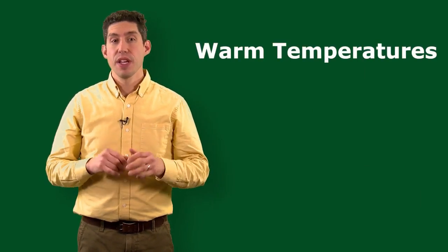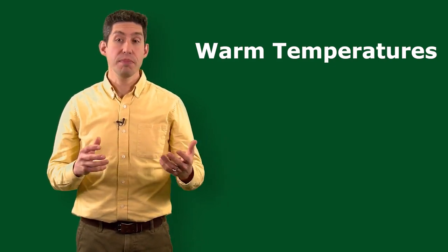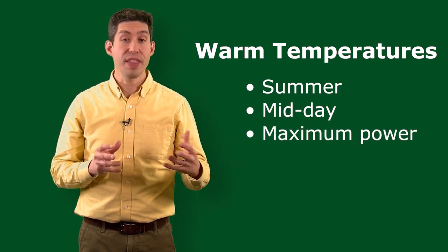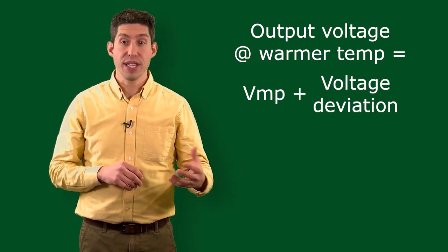Now let's do the calculation for warm weather conditions. The calculation is very similar, but we have to think about when warm weather conditions actually occur. Well, this is going to be typically during the summer at the highest point of the day, so the module is outputting a maximum power and thus a maximum voltage. So in this case, we'll be looking at the voltage at maximum power, or VMP, instead of the VOC.